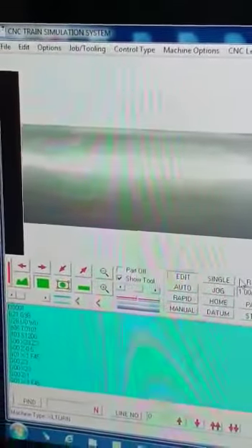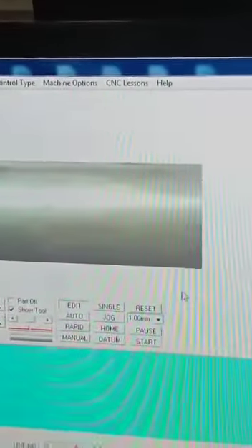Now again, you have to face up to 28. So you have to put a small cut. So G00 Z minus 0.1. So again what happened: the tool has come down to where you have to face. Now G01 is a linear interpolation. Now the tool must be facing this. So G01 X minus 1.